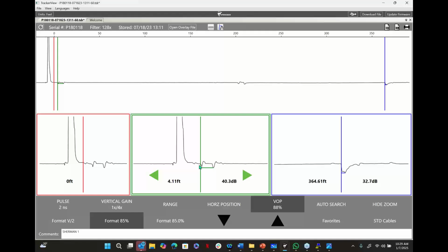We go ahead and take our shovel and start digging. And by the way, 4 feet is going to be right there, basically where I'm standing. We're just on the side of an apartment building, right? So I'm sitting here thinking, who was doing the testing here, right? So we start digging, and we're following the curve of the cable very gently right here. We're only maybe a foot into the ground at this point. And sure enough, just like I said earlier, right where that starts to curve right here, we shake off the dirt, we look at it, wipe off the cable. Sure enough, we find a hairline crack right there. And it was easy to find.